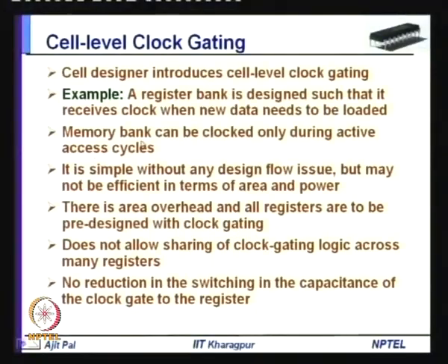Similarly, a memory block will receive clock only when that memory part is accessed. That means, the memory bank can be clocked only during active access cycles. So, within the memory bank the clock gating circuit is integrated.